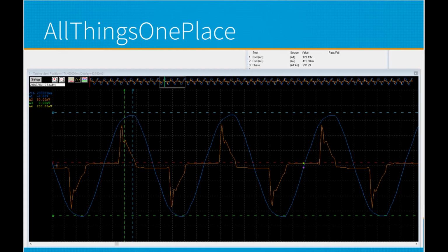And here it is. You can see it basically doesn't draw any current for a significant portion of the time, and then it just draws these giant spikes. And this is very much what a capacitor attached to a bridge rectifier looks like. So although this is a capacitive dropper, it almost appears like that part of the circuit isn't really doing anything. We're going to mess around with this and we'll see if we can make this look a little better.